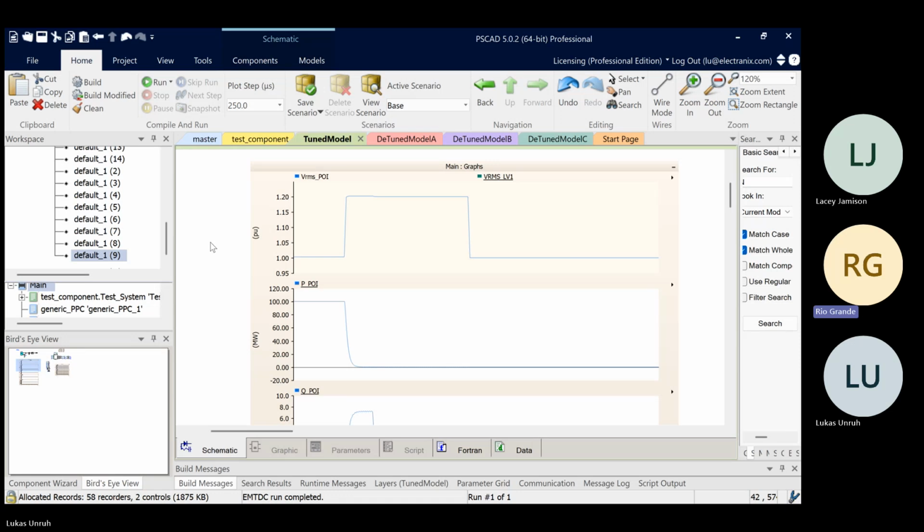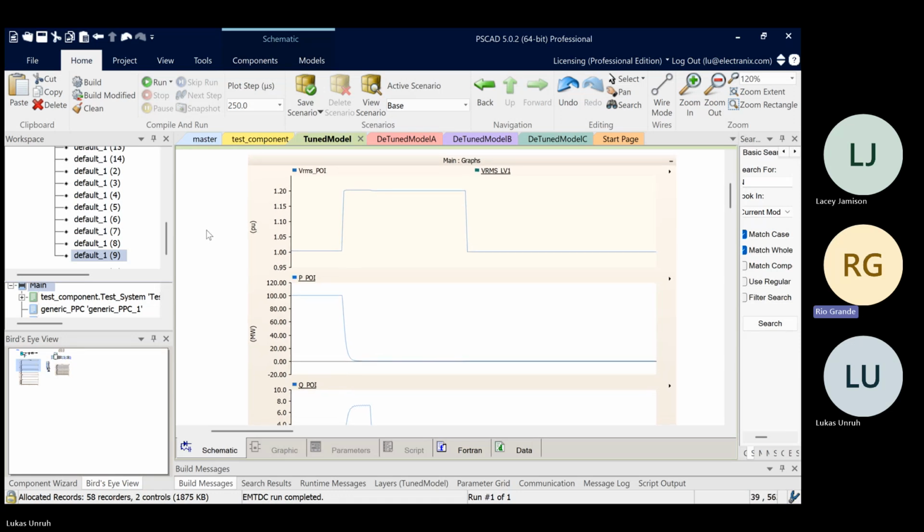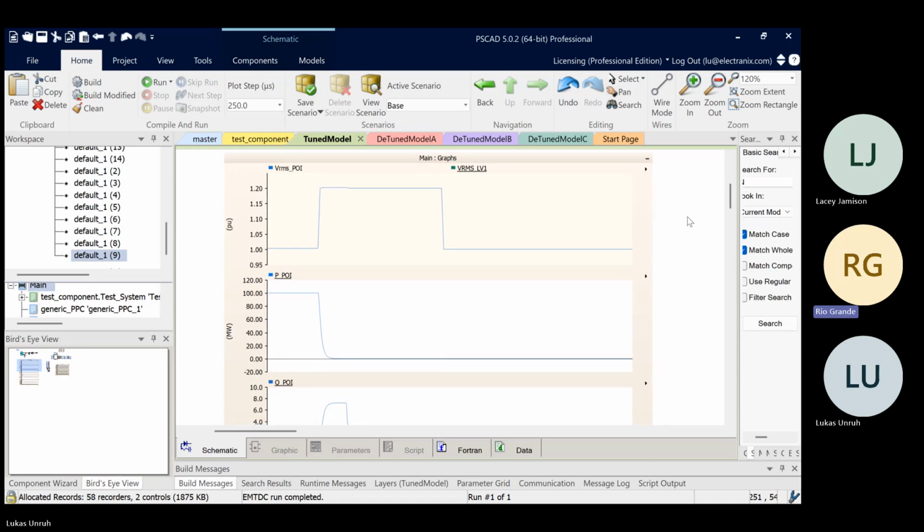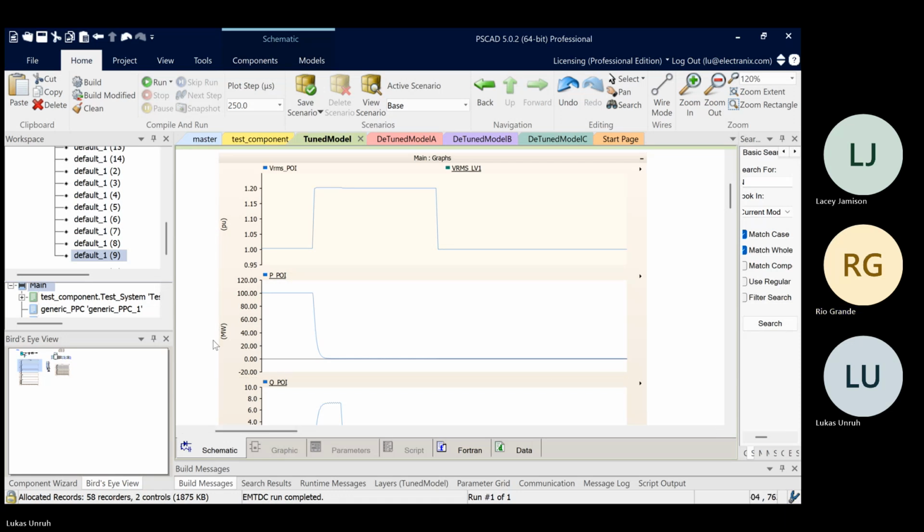If they tell you that's the equipment capability, then that's all you got. If they say, oh, we set it based on a PRC-024 ride-through curve or something like that, then you should see whether you can get that value increased to the capability of the equipment, so that you could avoid the trip. So there's two different ways you could possibly fix this if you ran into this in practice. Okay.